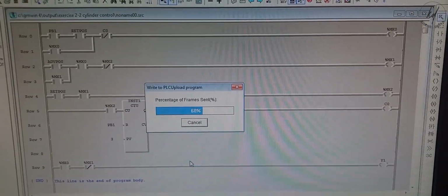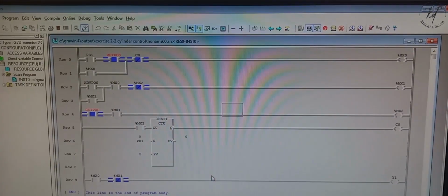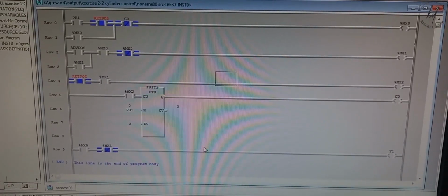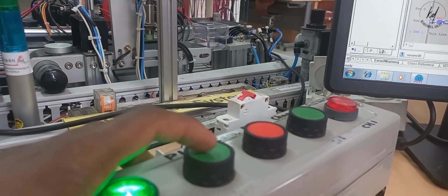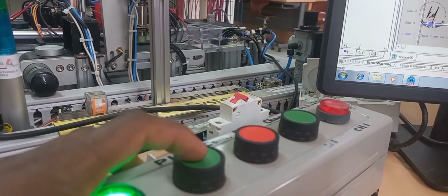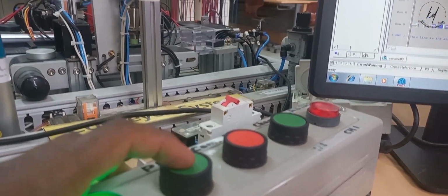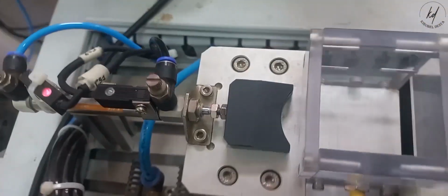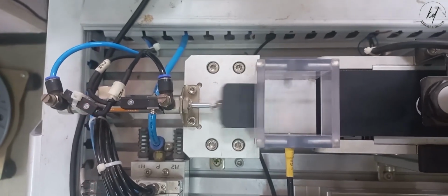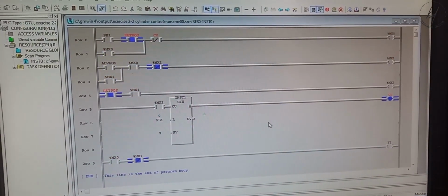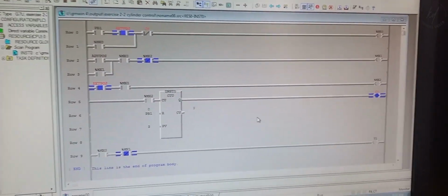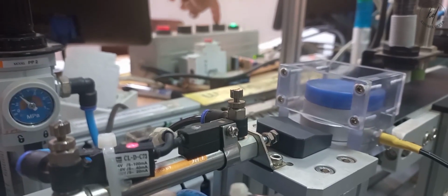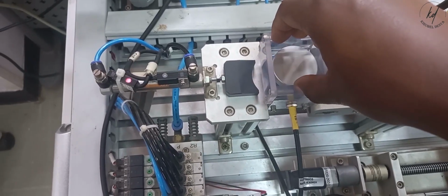As a result, the third memory address MX2 is the input for the counter to count, and as we see from the ladder diagram, it depends upon the memory address MX1 and the cylinder's piston having returned. This is detected by the retracted position sensor. This is achieved when MX1 and the retracted position sensor detection senses those two important conditions, and allows the supply cylinder piston to go on and off 3 times, and due to the normally closed contact of the up counter output connected in an interlock manner, the overall program ceases. So if the push button is pressed for the second time, it will result in 2 things. The first one is to reset the counter's current value to 0, and the second one would repeat the previously expressed execution.